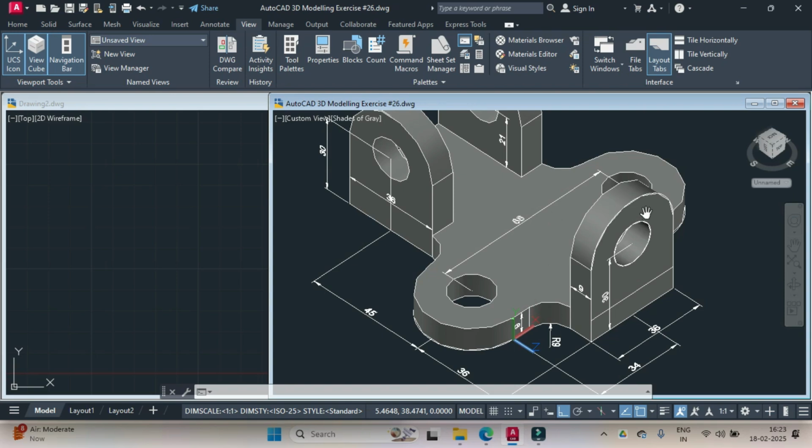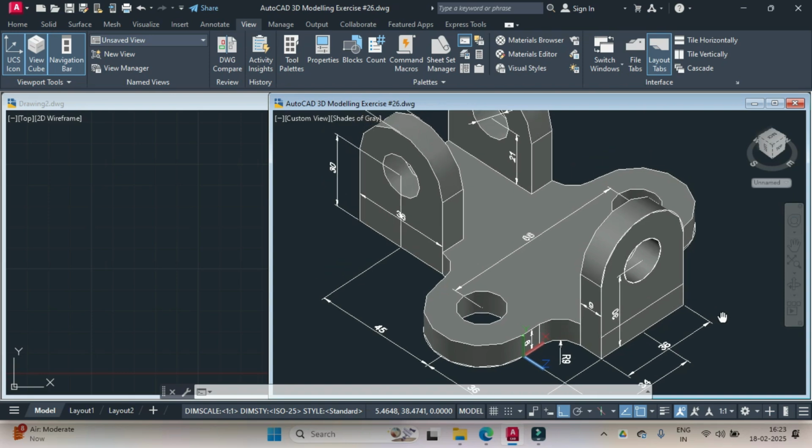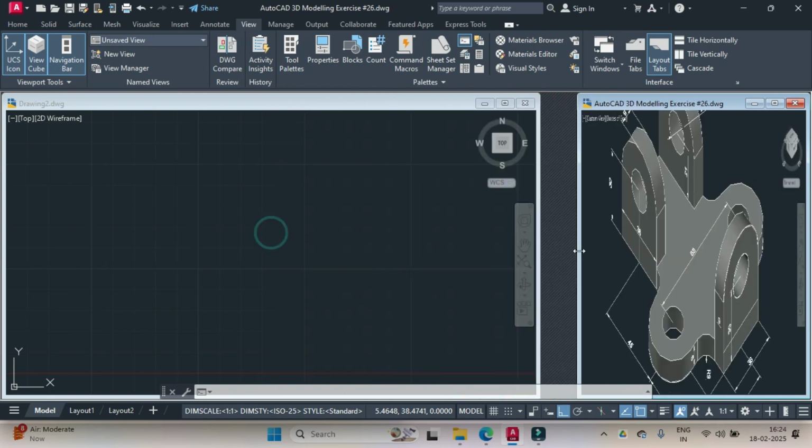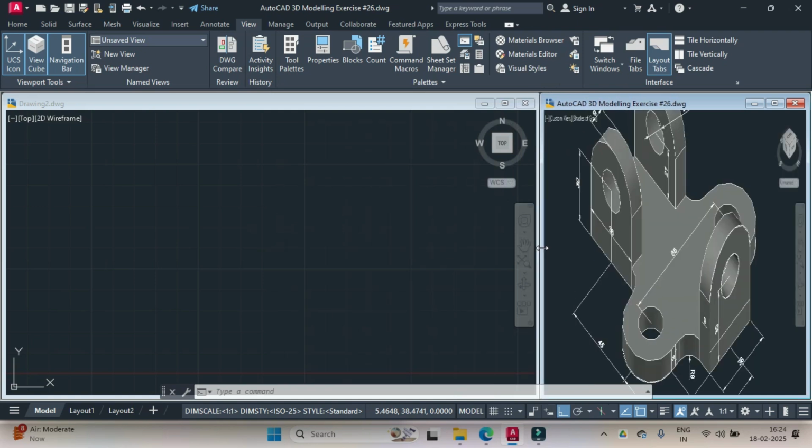Once we have drawn that, then we'll make this profile. So we'll change the view to left view and we'll begin by drawing this inner circle of 16 dia, outer circle of 36 dia, then drawing a line from the quadrant here downward to a distance of 21 units, to the right 36 units, back to the quadrant of this circle. Trim the unwanted part of the circle, press pull it to 9 units thickness, and then copy this entity here, here and here, and we are done. So let me show you how we'll proceed with the drafting.